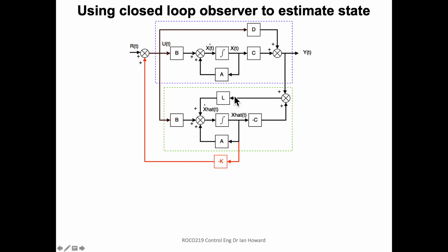And now we're scaling this prediction error, and we're using that to feed back into the system here in order to actually try to minimize the prediction error. And then just in the same way, we're using the x-hat for state feedback control. So we've added this little controller loop here in order to make sure that the system actually does a better job predicting than it would have done otherwise. And another nice aspect of this is that if the feed-forward system was actually unstable, this can actually stabilize it as well.